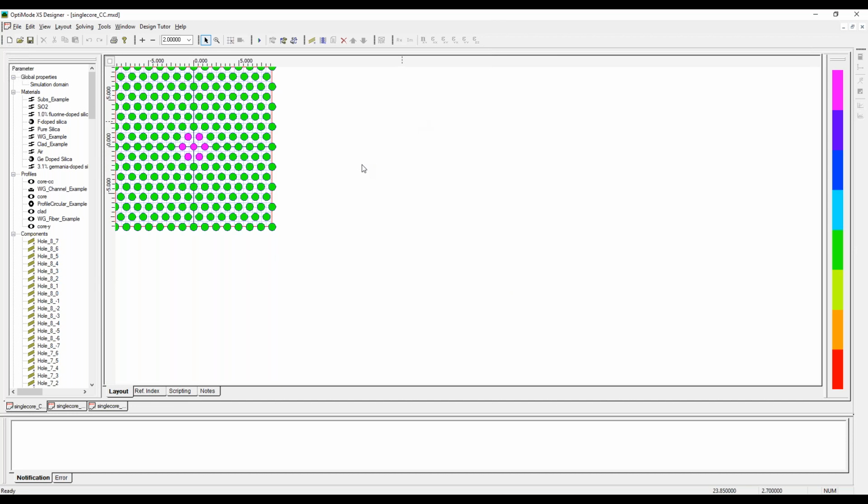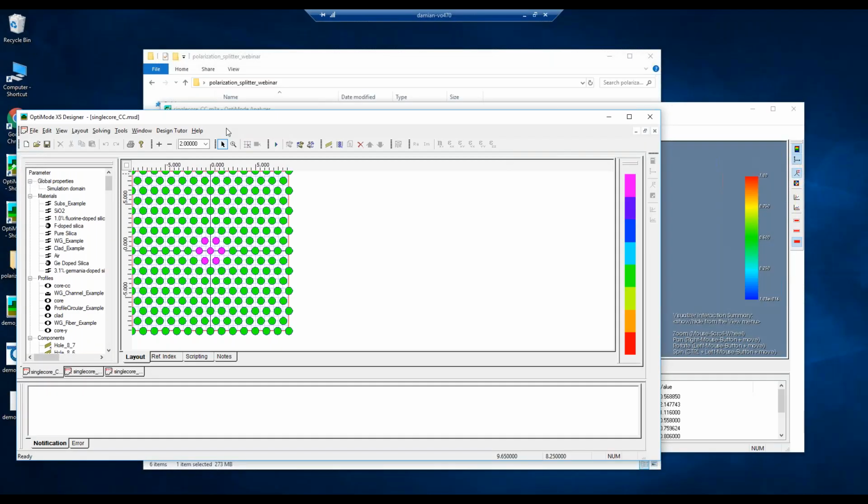Right, so I ran the simulations. I used some tricks with boundary conditions to reduce the domain. Since it's symmetric in X and Y, in this case, you can reduce the domain by 4 and also kind of filter out some of the modes that you want. I can show you that in a sec. But first, let's look at some of the results.